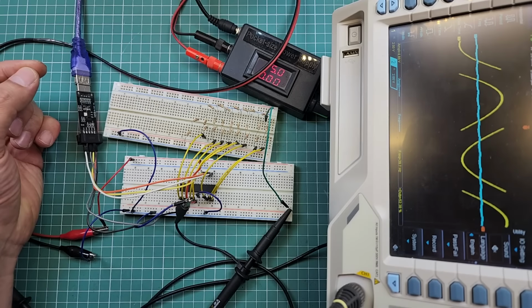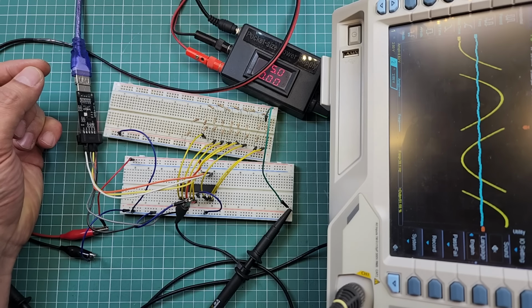Lower resistance values will result in lower output impedance, and higher values will result in higher output impedance. The output impedance is not a big problem because it can be reduced by using an op-amp. It's very easy. Anyway, this was a way to make analog voltages like a music signal using resistors.